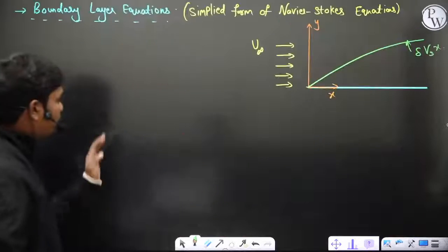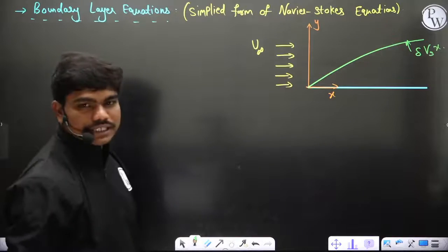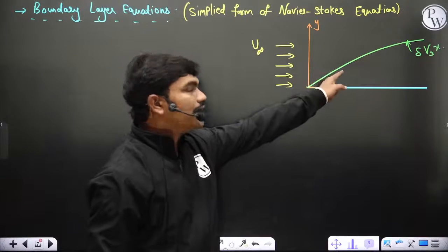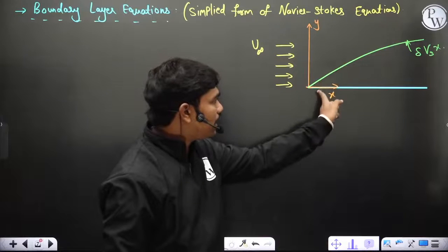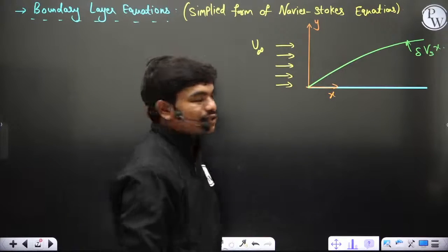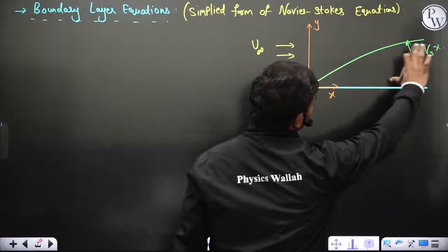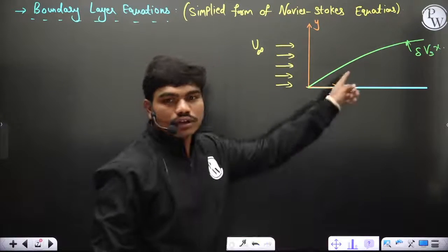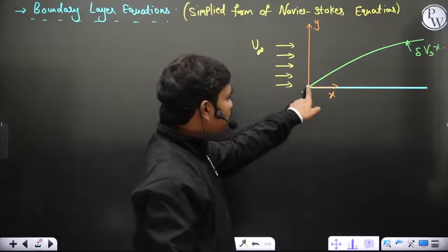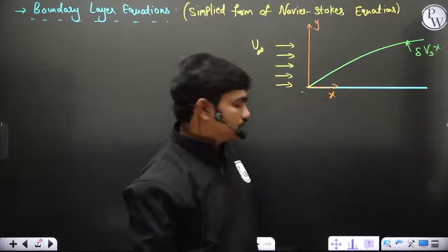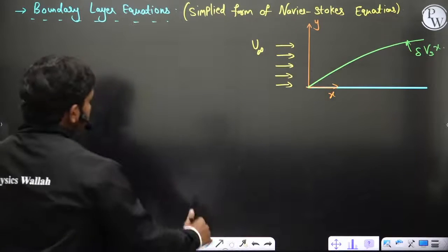Okay, now coming to this, so that's delta versus x. Right now we don't know what is the equation for this delta versus x, but what you can say is that this delta will actually increase as x increases. Okay, so this is the boundary layer thickness variation with respect to x. It's not the fluid particle. Understand, many of you might have a wrong intuition that the fluid comes like this, hits the plate and moves like this. Okay, no, that's not the case. Clear?